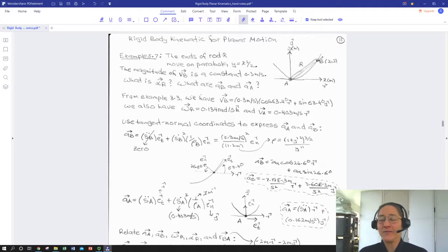We're going to have that the acceleration A of one point on our rigid body is 0, so the motion of the other is just going to be due to the alpha and omega contributions. But we need to know angular velocities and angular acceleration, which we may have to infer from something else. In fact, we will. So we have our full velocity at B. It's 0.3 meters per second, and it's directed tangent to whatever the path is here.